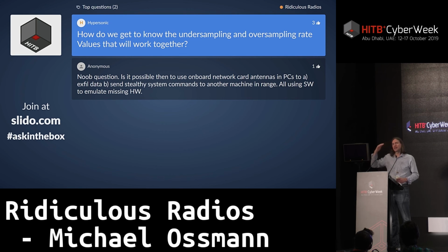And if I remember correctly, we were sampling at something like 20 megahertz. We were sampling that ADC pin, or that GPIO pin. And generally speaking, you can get away with undersampling, but only a few times your sample rate. So we were about half the sample rate. Our sample rate was about half the frequency of our target, and that worked okay.